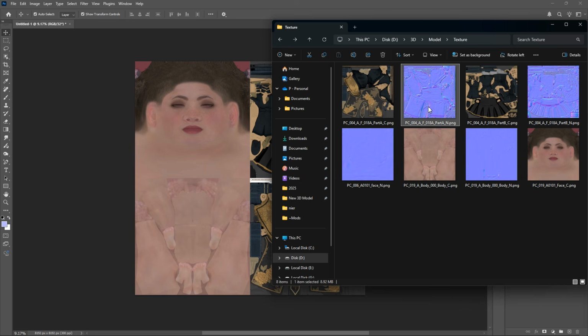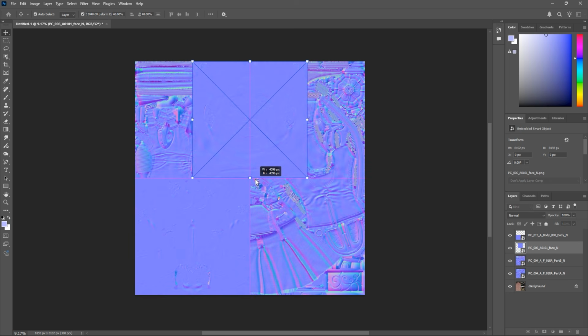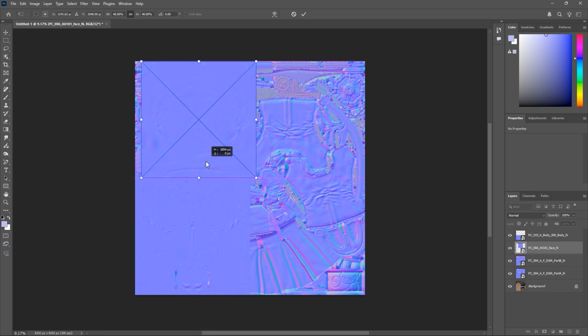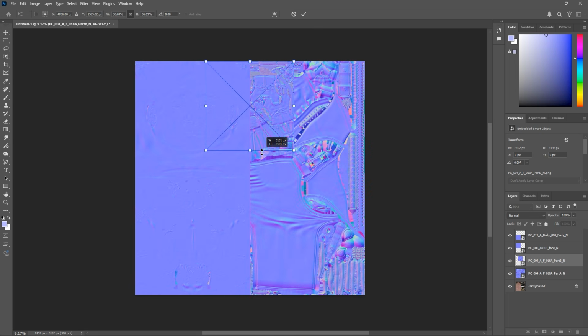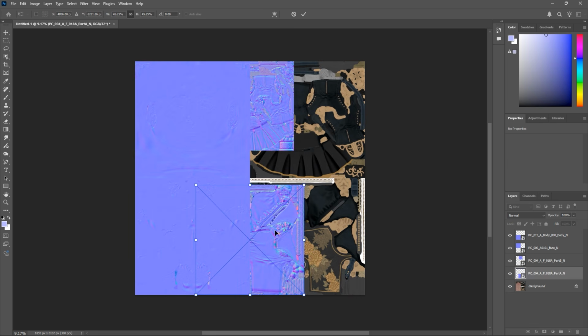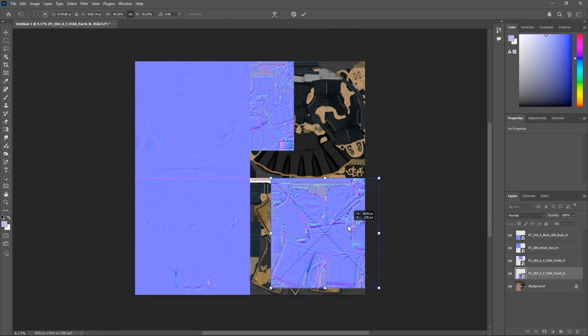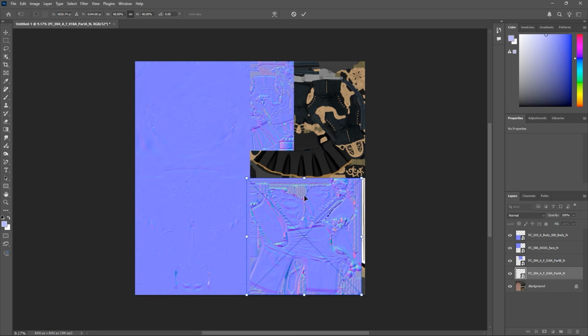Before we jump into Blender, make sure to repeat this process for your normal maps, roughness, or any texture types you have. Base color and normal map usually is enough. When merging the other textures, use the exact same layout and the size you used for the base color textures. You can keep the base color atlas open in Photoshop, like this, and use it as your guide to position everything correctly. You can easily tell which normal map is for which base color, and set them up.